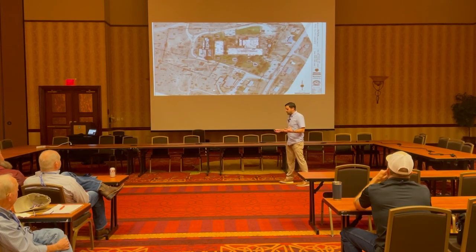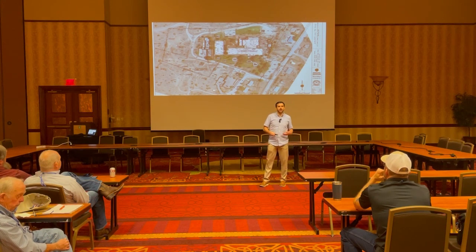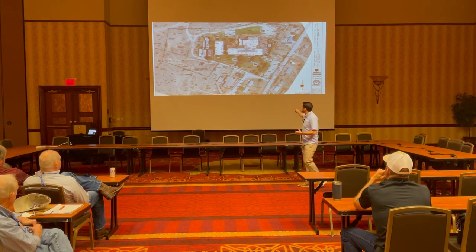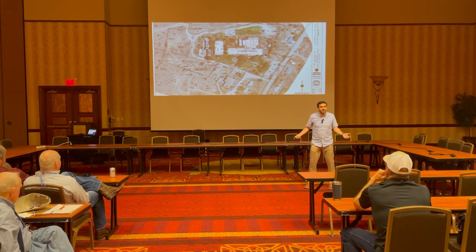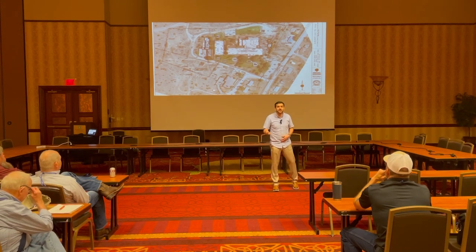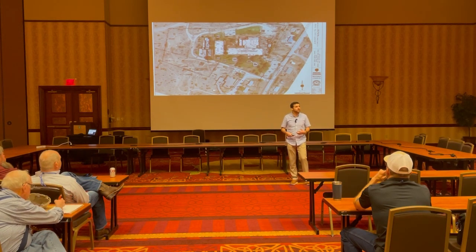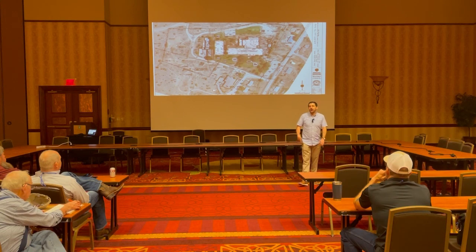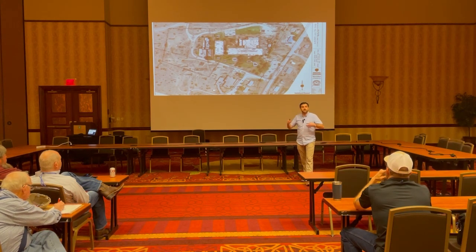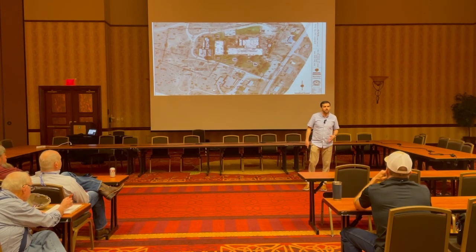Because at the end of the day, my goal is not to talk about how cool drone technology is, it's to tell you how most efficiently to get to a final survey. Is it from a drone? Is it from the ground? Well, it might say that in the notes, but you really don't know. And the answer is probably a little bit of both. Drones are really great for topo, but they're not going to know boundary. So you shoot boundary on the ground, you put it all together. Some stuff you do on the ground, some stuff you do from the air. And the goal is to get to a survey as efficiently as possible.